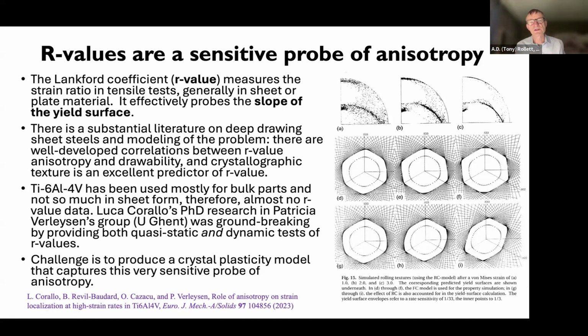And I realize that a yield surface is a rather specialized topic. But for those of you that have seen a yield surface, this is actually a pi-plane yield surface. And when you have a strong texture, you get really quite sharp corners in this yield stress. So what does a corner mean? A corner means that if you stress the material and you go out in this direction, then the strain rate that you get from that is perpendicular, normal to the edge of that yield surface, the yield line, or the yield locus.